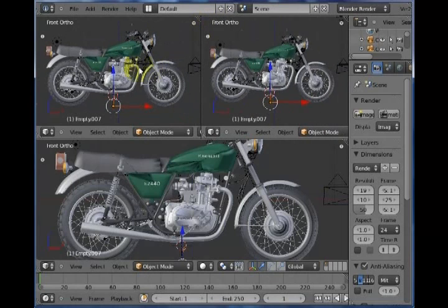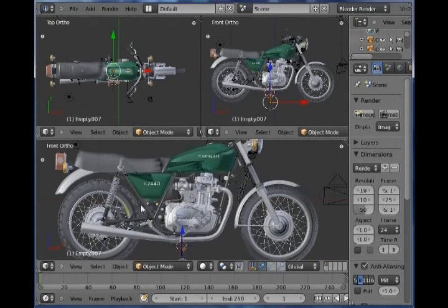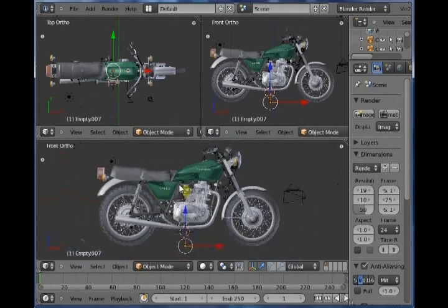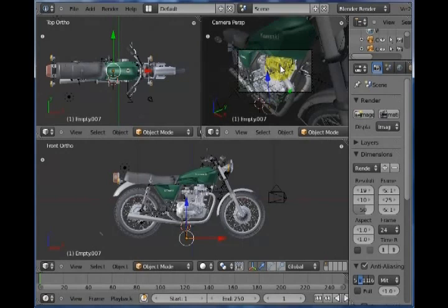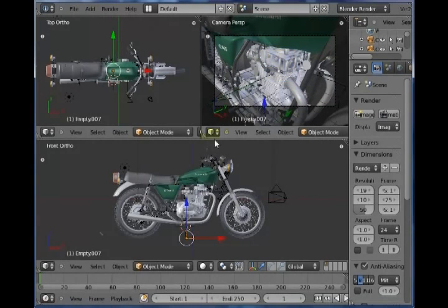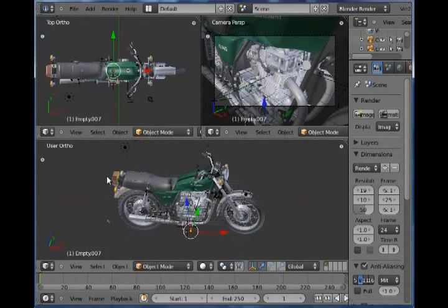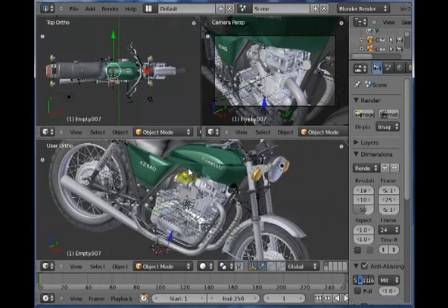Okay, let's grab this triangle again, and let's split my viewport in half. So now I have 3 viewports, so maybe I would want this one to be a number 7. I'll put my cursor down in this one, and again hit number 1, which I'm already in. Let's say I want a camera viewport here, I could hit number 0, and now I'm in a camera viewport in this one. So as I work, and as I move things around, things are going to go a lot nicer for me as I go through selections.